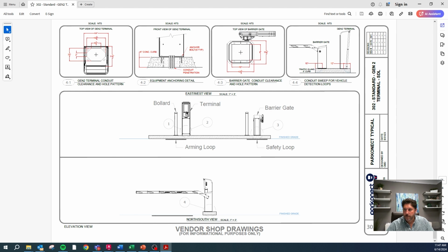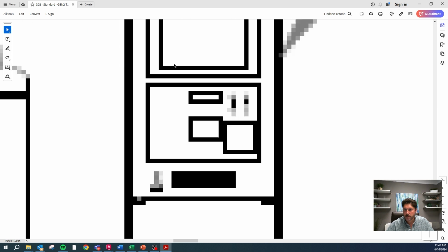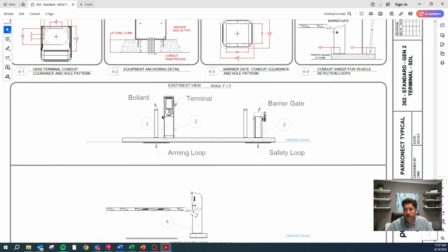And there's two types of PDFs, a vector-based PDF, which is what this is, where you can see that it doesn't matter how much you zoom in, it's still crystal clear. Whereas an image is made of pixels, and if you zoom it just gets more pixelated. But since this is vector-based, it has lines with vectors on it. We can import that into CAD, and CAD will infer lines and line types from that.